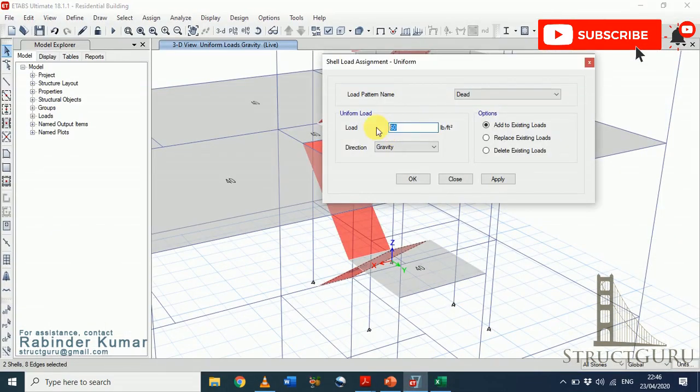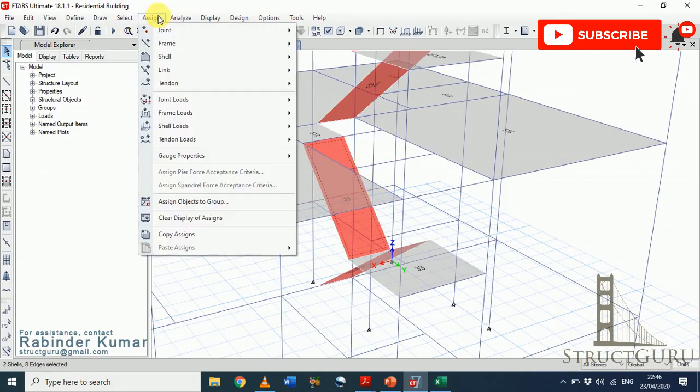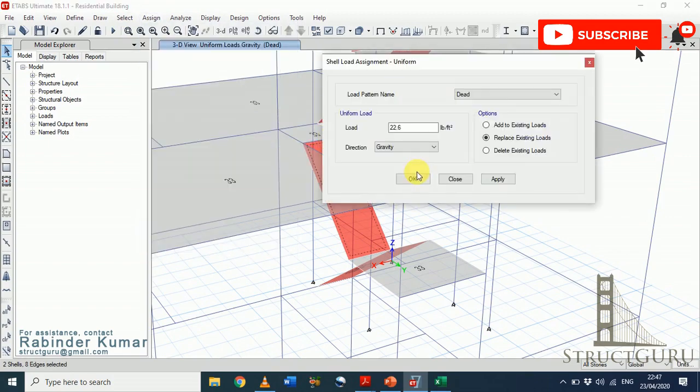So the step load for first flight is 22.6. Click OK, close. Now select second flight, go to assign menu, shell loads, uniform, 30.27. Click OK.